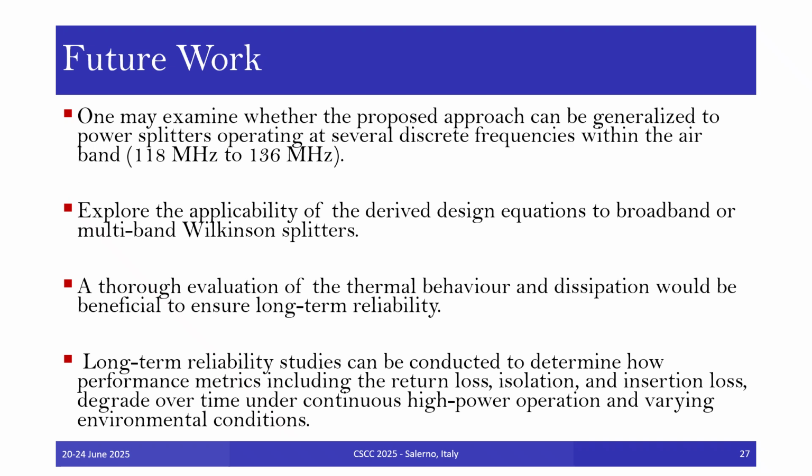This may involve modifying the lambda quarter wavelength equivalent circuit to maintain low return loss and high isolation over a wide frequency range. Since the design targets high power operation at VHF, a thorough evaluation of the thermal behavior and dissipation, especially in the resistors and inductors, would be beneficial to ensure long-term reliability.